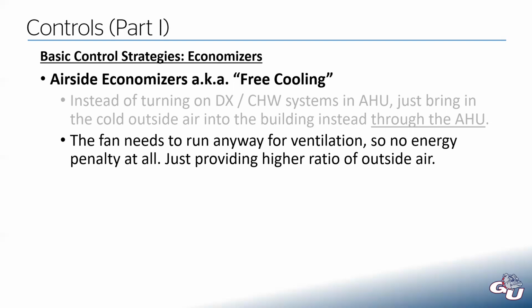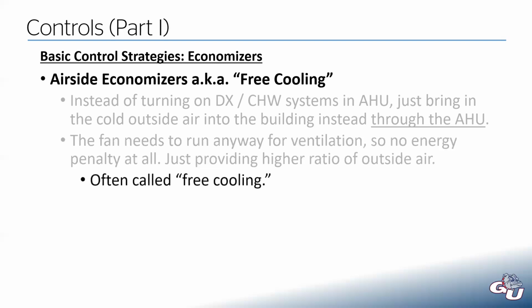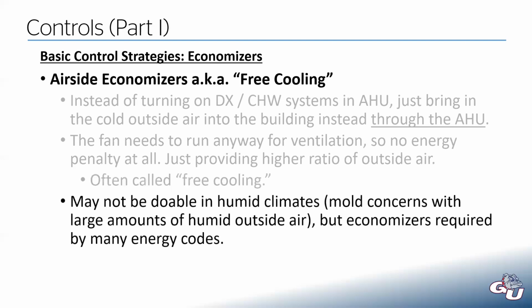All we're doing is providing a higher ratio of outside air. So that's where this term free cooling comes from. We have to run the fan anyway. There's no other penalty that we have to pay. But it might not be doable if you're in a humid climate. If you pump in a bunch of humid outside air into a building, you're asking for mold problems. But in a lot of other areas of the country, economizers are required by many energy codes out there.